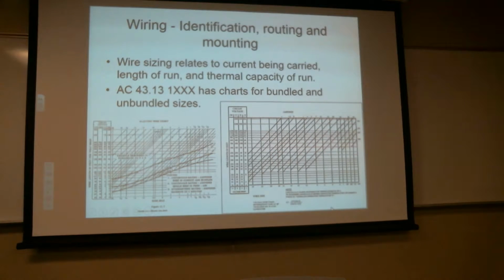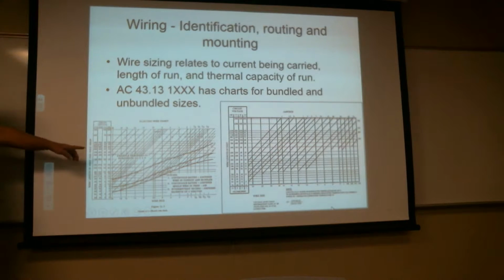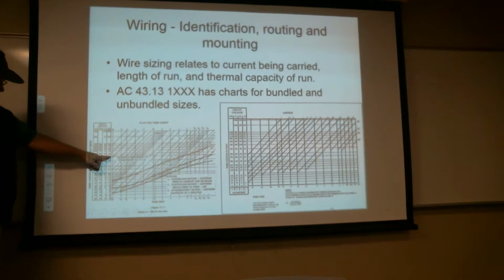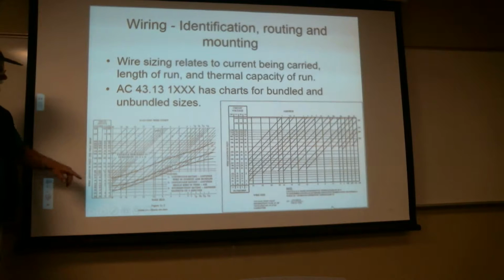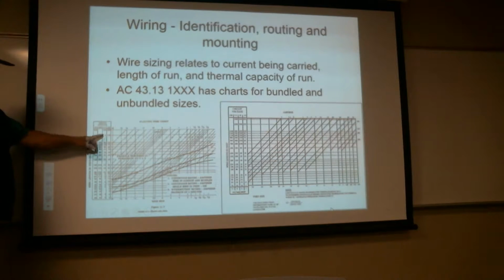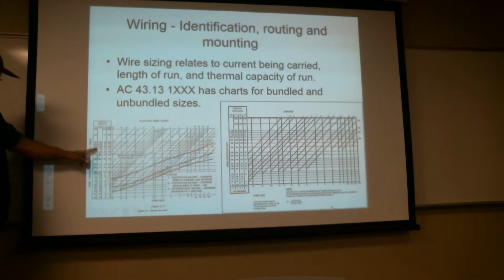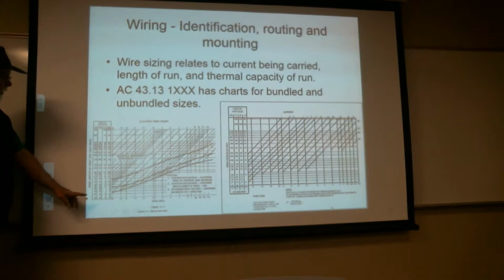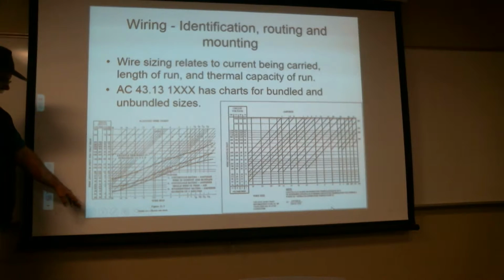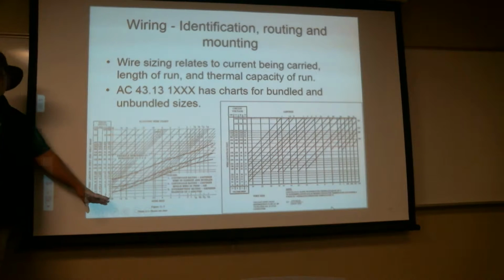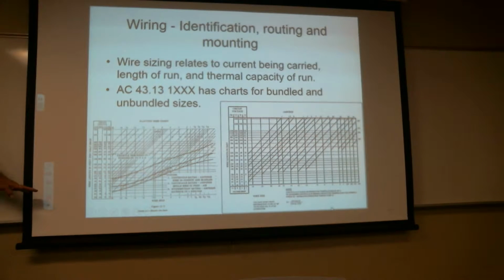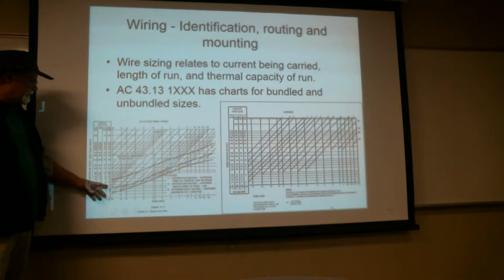What do you mean 50? Is that the length of it? The length is 50 feet, for 12 volts, or in this case, 28 volts. 25 feet, and that's to achieve no more than, and this actually clipped the bottom of it, a 5% voltage drop. So that's what the chart is based on.